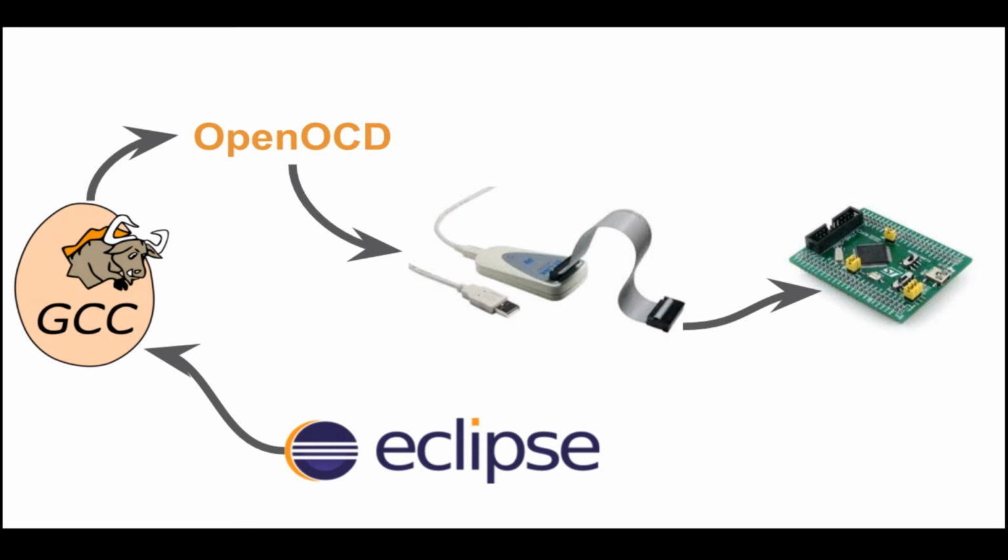Here I've got a picture of a prototype board, but it could be an individual IC with minimal circuits built with clock signals and other power and whatever is necessary for an individual IC. And mostly this interface between the programmer and the IC will be through SPI, standard serial protocols, which would flash the binary or the program into the IC. So that's how the whole thing works.